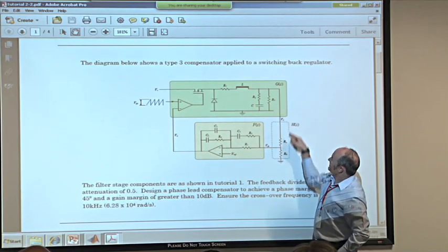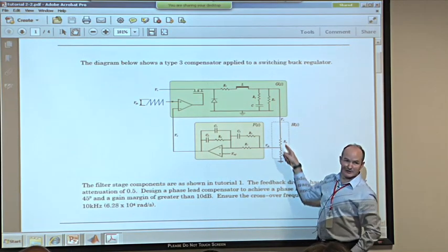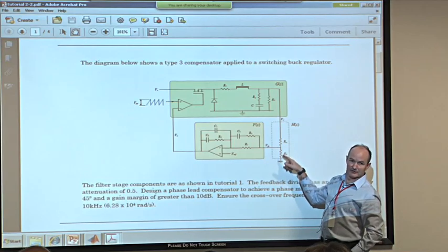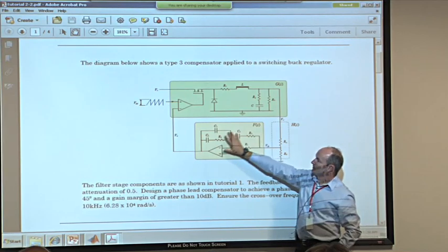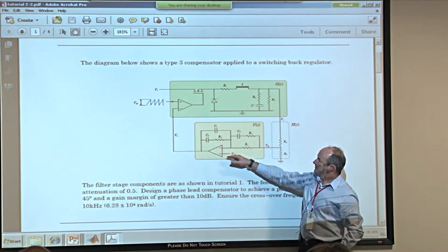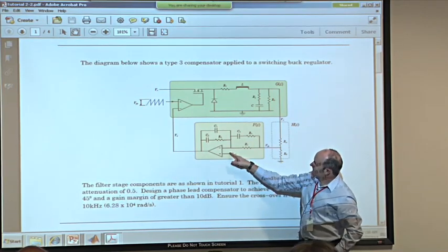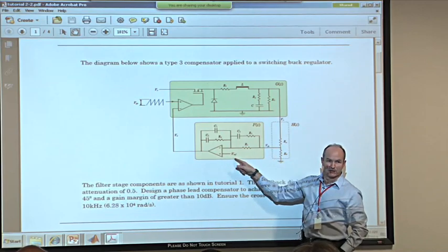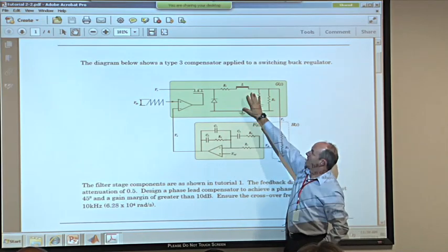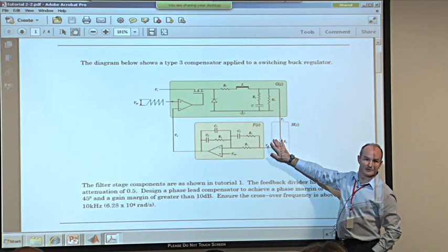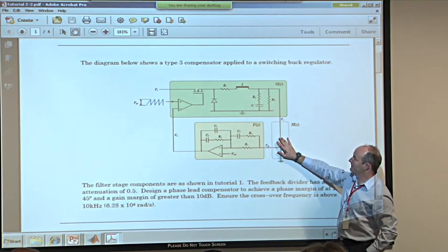And there is a feedback. So the output voltage is measured. It's attenuated through this resistive divider. And then there is a compensating network here, which produces an output based on the feedback. And this is the voltage reference coming in. So this is the controller. That's the plant. That's the sensor in terms of a classical canonical loop.